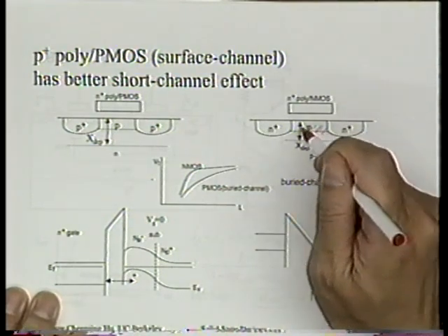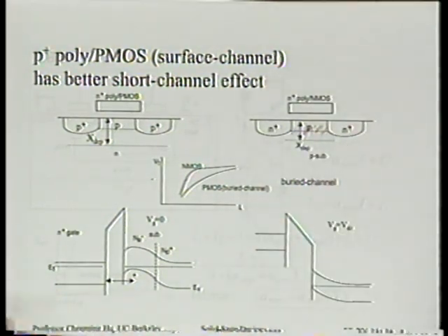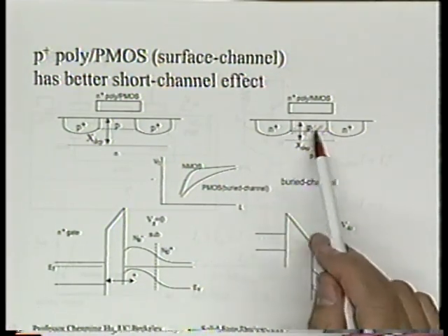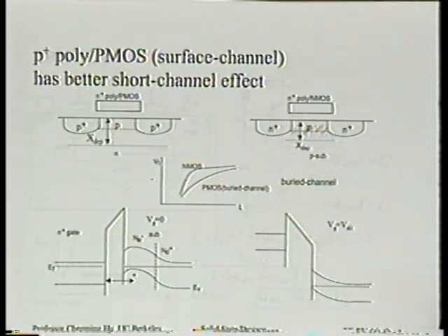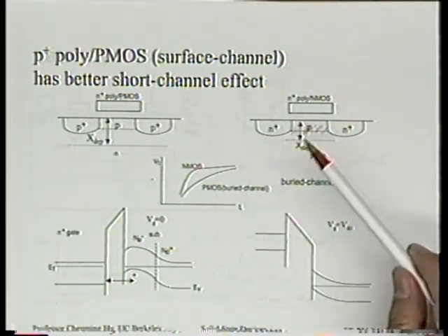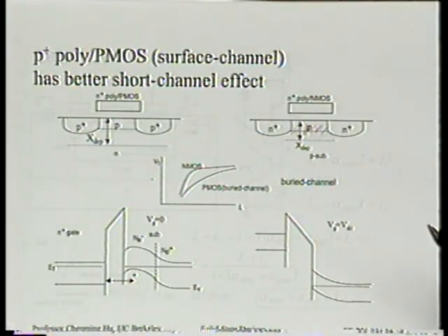You know, with the newer style of retrograde, well, we shouldn't really think we have a boron implanted layer in the N-channel transistor, although earlier the N-channel transistor indeed had a boron implantation layer near the surface to bring the threshold voltage up. Okay, today we don't do that anymore.